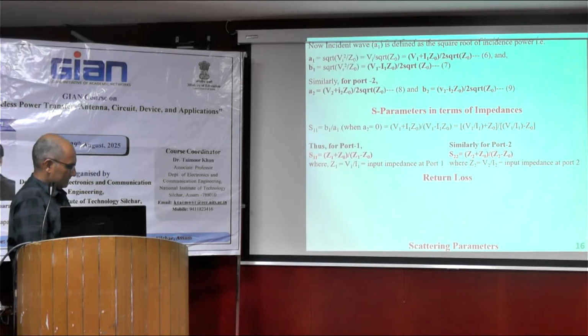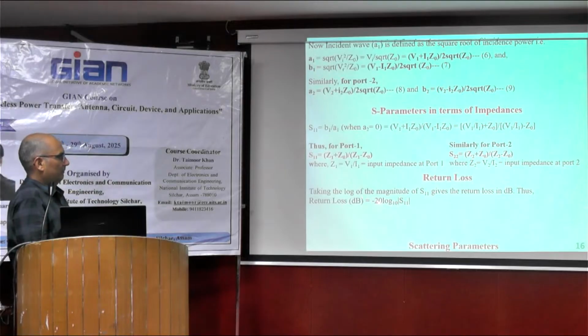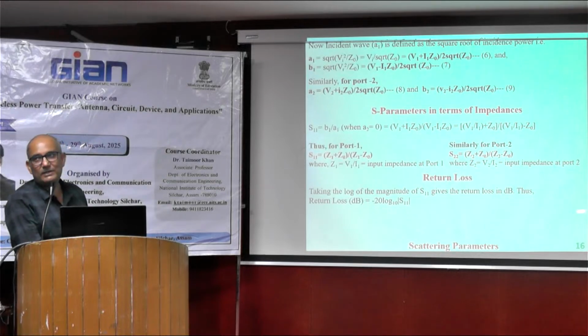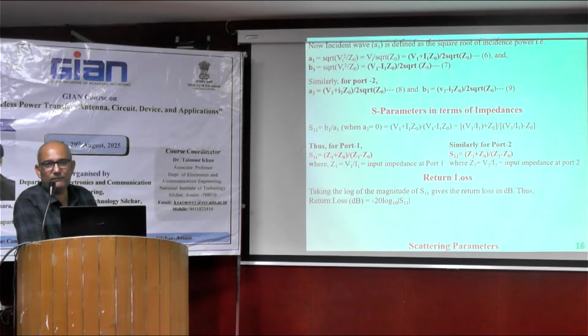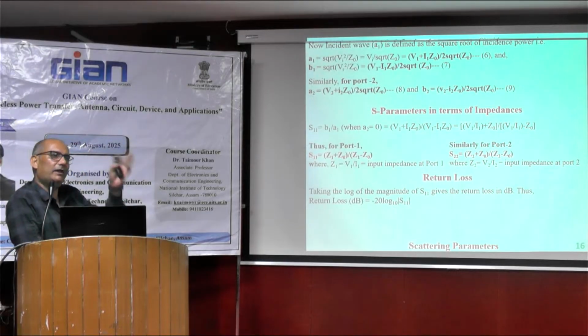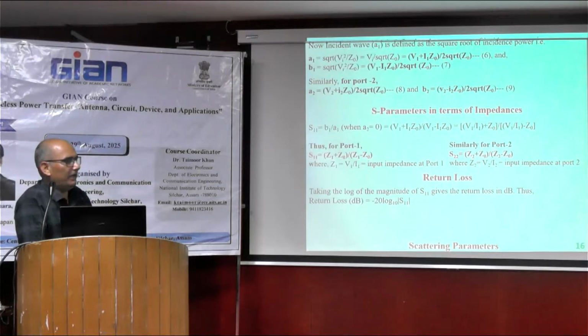Now return loss will be minus 20 log base 10 of S11. This behavior should always be positive. Then it is meaningful. Then you can convert this reflection coefficient dB value into linear scale. Then you will realize that one is feasible, and the other quantity will not be feasible if that plus to minus sign is changed.